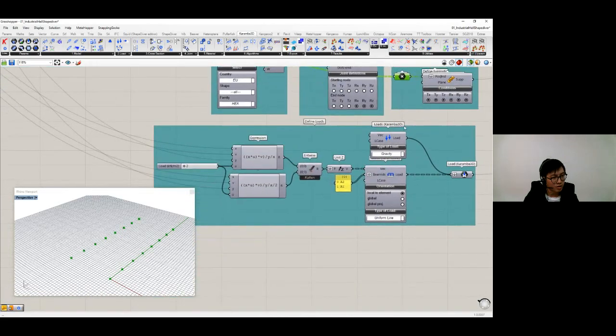Lastly, we need to define our loads. As I said, I split the beams into A1 and A2, where I calculated the load. Here I have a mesh load of 2 kilonewtons per square meter, and I distribute them accordingly onto my beam elements with these two equations. So here in the end, if I look into my output, I have 7.14 kilonewtons per meter on our A2 elements and 3.57 kilonewtons per meter on our A1 elements.